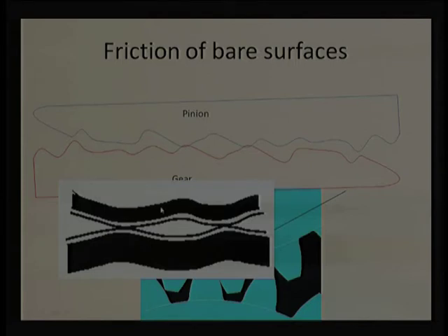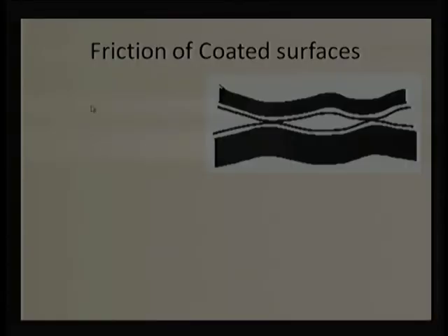And this has been studied in our friction module lectures, maybe the third, fourth lecture, which was discussed in detail, that if there is a bare surface kept in the environment, there will be some sort of oxidation, and that oxidation itself will generate a low shear strength lubricant layer on the surface, but still this can be treated as dry lubrication. Now, as it has been shown that there is a contamination layer, the question comes: can we really go ahead and design this lubricant layer on our own using some sort of solid lubricant?